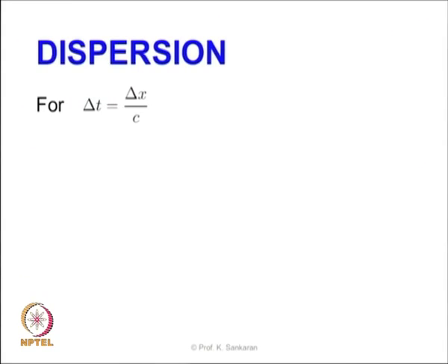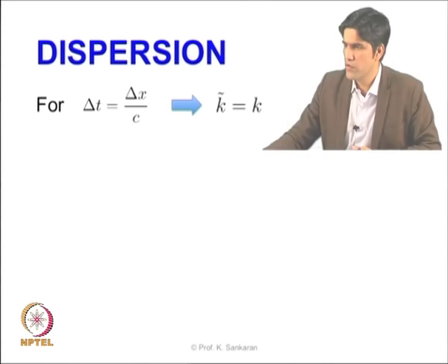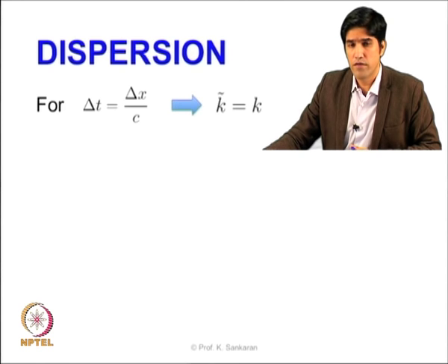So if you choose delta t equal to delta x by c, you will get the analytical solution and the numerical solution will be correct. But obviously we cannot do this because of numerical stability issues. So we cannot go at the exact delta x by c time stepping. So we have to reduce the value of time stepping by a certain fraction of the delta x by c.